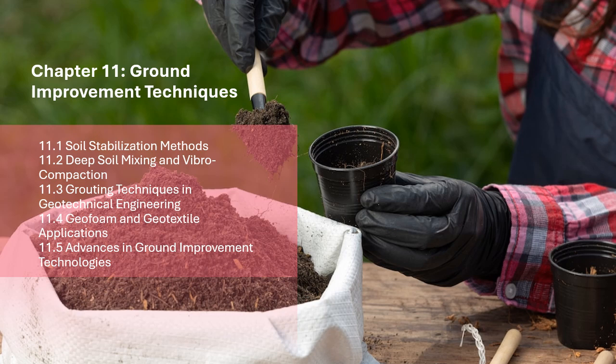1. Cement grouting. Cement grouting involves injecting a cement slurry into the soil to form a solidified mass that increases the soil's strength and reduces its permeability. Purpose.